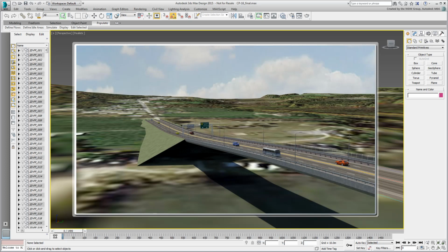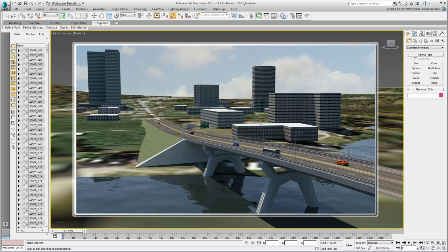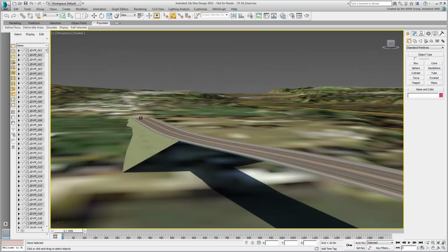In this case, you add custom pillars to the Civil View library, so you can use them in this project or any other. From that point on, you continue embellishing the scene using Civil View along with other simple 3ds Max techniques. After adding a convincing animated water surface, you add a few background objects such as buildings and trees. You scatter the trees using 3ds Max's Object Paint tool to control their positioning. Finally, you create animated camera shots to bring the scene to life.